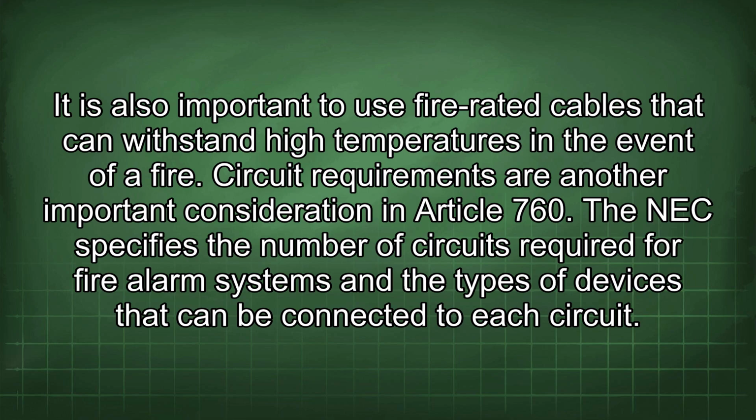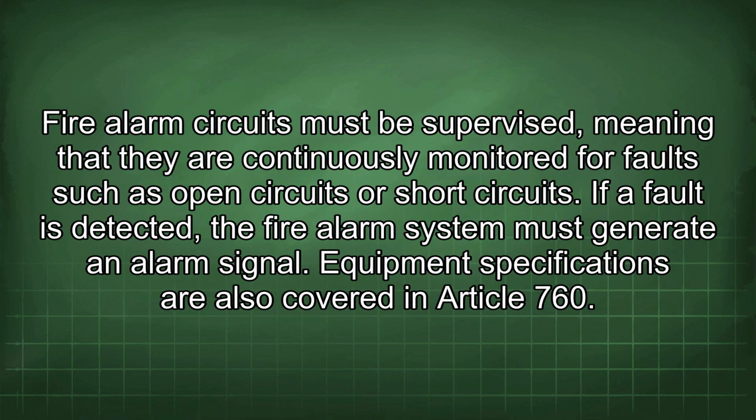Circuit requirements are another important consideration in Article 760. The NEC specifies the number of circuits required for fire alarm systems and the types of devices that can be connected to each circuit. Fire alarm circuits must be supervised, meaning that they are continuously monitored for faults such as open circuits or short circuits. If a fault is detected, the fire alarm system must generate an alarm signal.